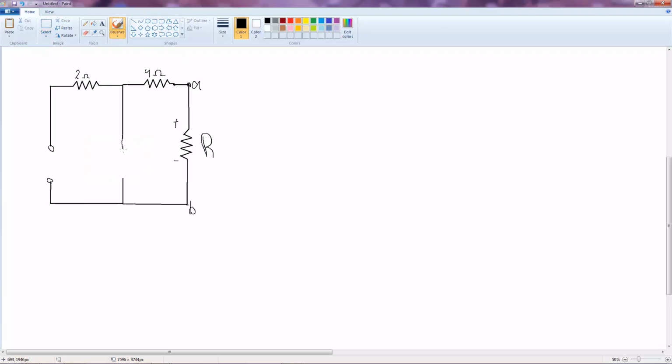So basically you put a wire instead of the voltage source, and you put empty space instead of the current source. And from here, if you had some complex stuff, you just have to add resistors in series and in parallel, and eventually find R Thevenin.